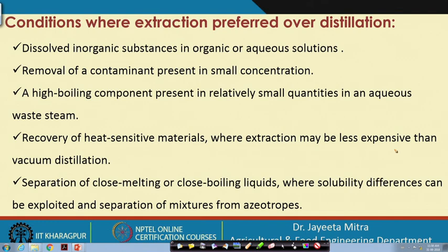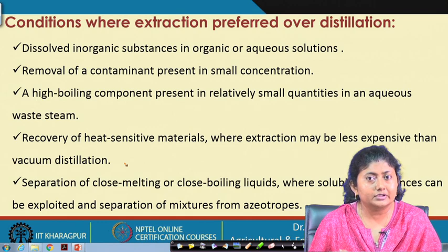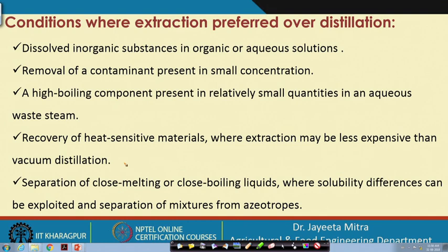Okay. And because extraction is less expensive compared to vacuum distillation. If you want to have distillation at lower temperature, we can lower the pressure in the chamber, that is increase the vacuum level, and then we can have distillation at lower temperature, but compared to that, extraction will be less expensive and beneficial in such cases for heat sensitive material separation.